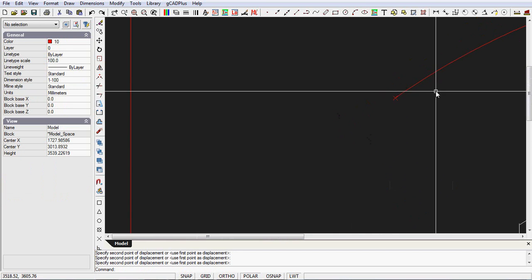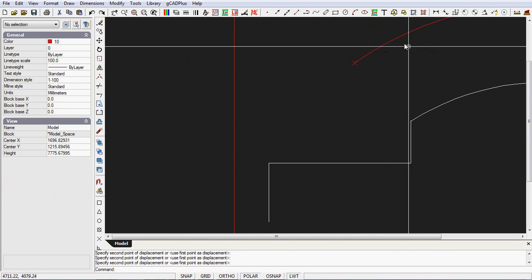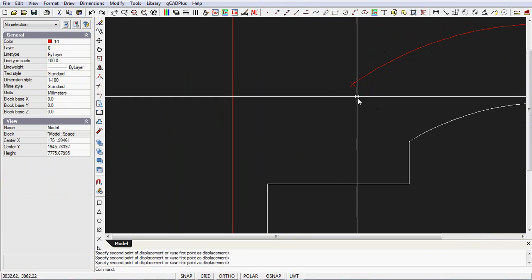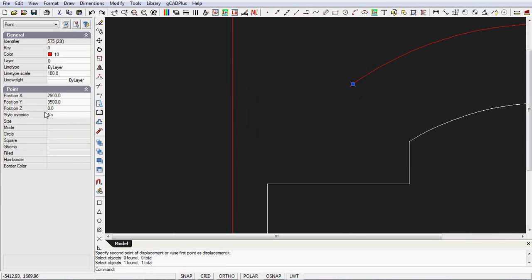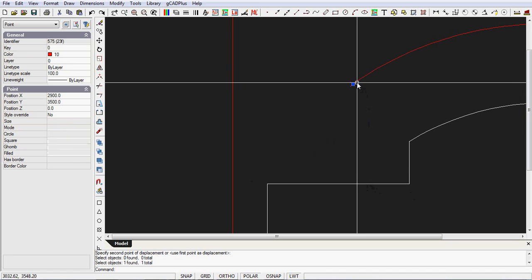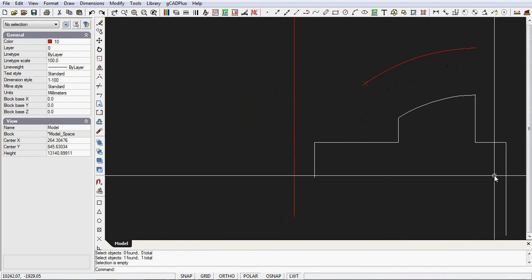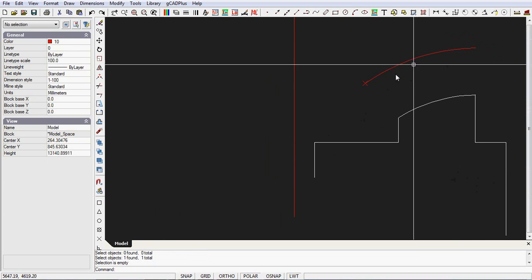Now our arc still reflects the shape of the building, but it's now got a convenient start point. Your construction team can simply measure quite easily from position 2900, so measure down here 2900 and up there 3500. So they're locating an arc, which is really difficult to locate. You clearly can't drive a peg in the middle of the house and swing an arc from it.